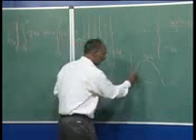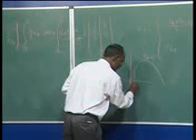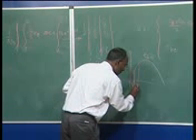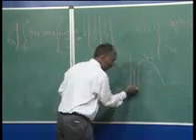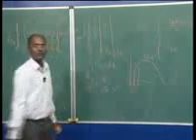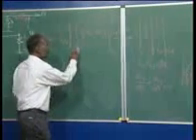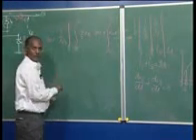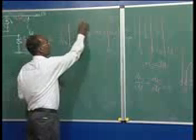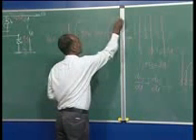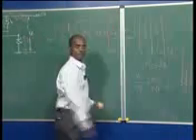Once you delay, then when 3 is fired, the commutation will occur for the u period, and for the remaining period the u will be over. So here instead of 0, I can start with the alpha degree, and alpha will be added here, here, and here.